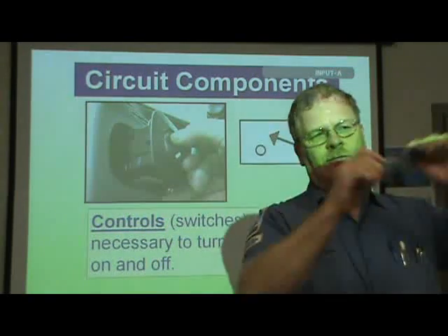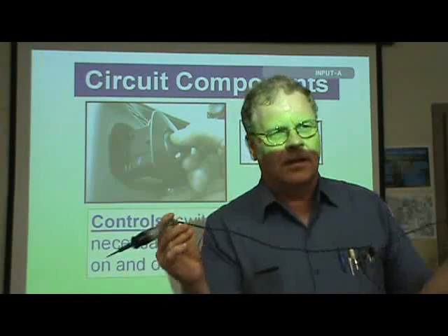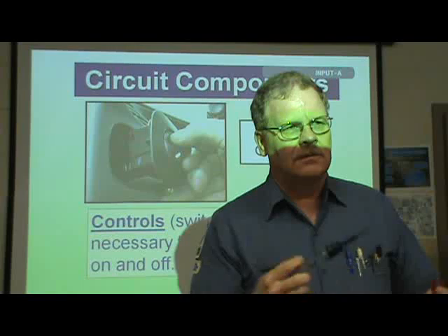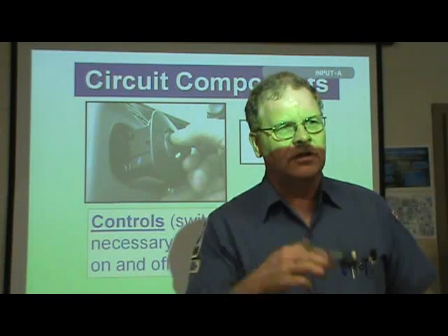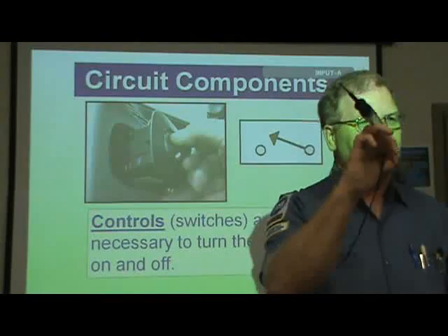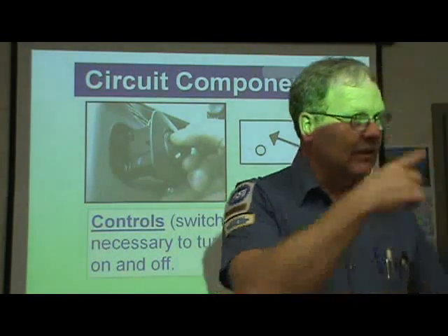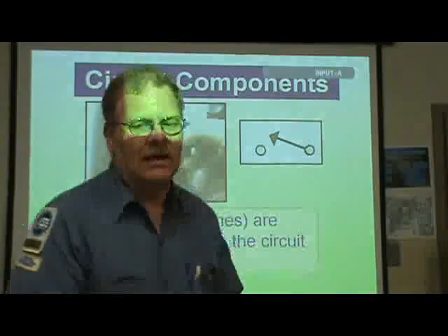What's the explanation for the light coming on? Because I could have looked up negative, it should show positive, like energy coming from it. It should go through the engine block instead of the test line. The only path to ground it has is through this little bulb, and the starter's not going to spin if it's going through the bulb. It's got to go through the engine block. It's not making it to the engine block.